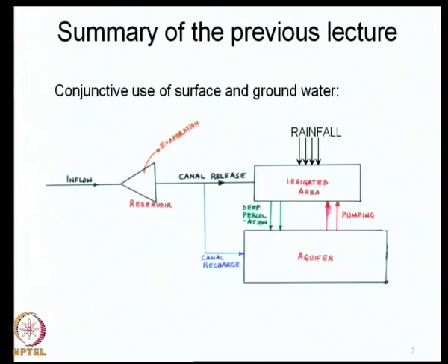I mentioned towards the end of the last lecture that you can make the groundwater model as sophisticated as you desire by including, let us say, the two-dimensional groundwater flow equations and then dividing this aquifer into a number of elements, and you use the finite element method to solve the differential equations. When you do that, you must write these balance equations corresponding to each of the elements.